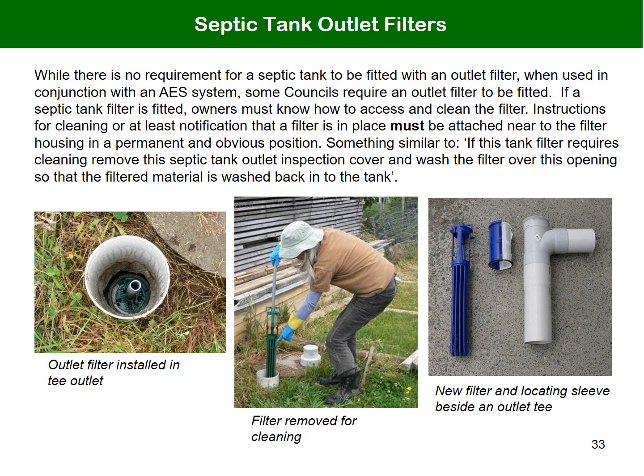Something similar to: if this tank filter requires cleaning, remove this septic tank outlet inspection cover and wash the filter over this opening so that the filtered material is washed back into the tank.